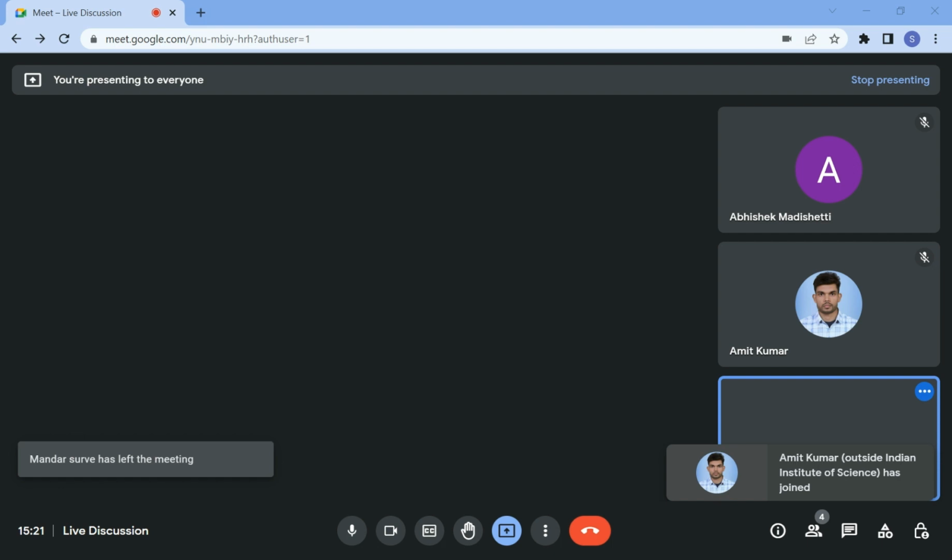This is a special case that I've drawn, but wherever I rotate it, somewhere I'll get that the front view makes angle 55. So right now I have made an angle of 45 with respect to VP. When I rotate this, somewhere I'll get the point B such that all these conditions are satisfied. And this is the second locus of B in the vertical plane.